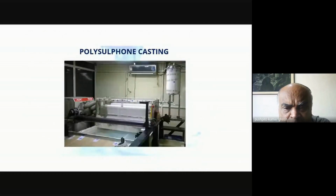In fact, let me show you some photographs. So this is how the polysulfone is being cast, this polysulfone layer on the non-woven fabric. Now, most important is this room, where you are doing all this casting. You have to have an excellent control over things like the humidity and temperature. In fact, it took us a long time to figure out all these things.